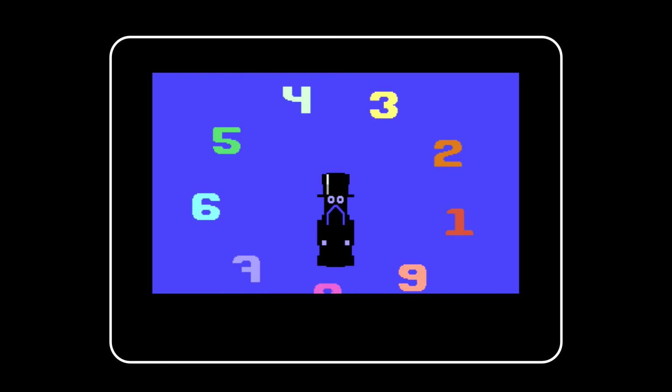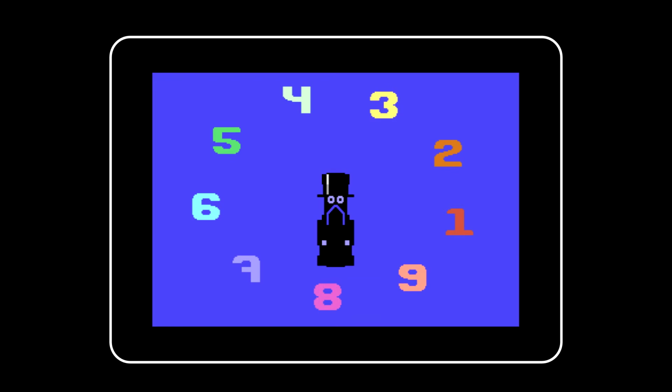The 9 sprites appear, but so far you're looking at a perfectly mundane thing called sprite multiplexing. And if you've ever played a C64 game with more than 8 things moving around on the screen, you've seen it. The idea is to reuse sprite hardware while the video frame is being rendered. As each frame is generated from top to bottom, the CPU can sync up with the video beam and change the hardware registers on the fly.